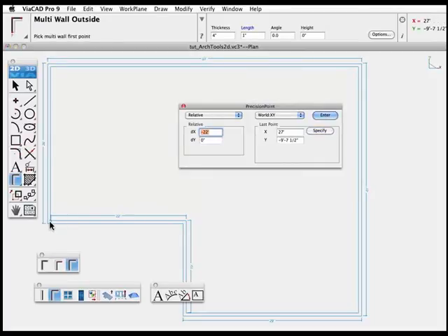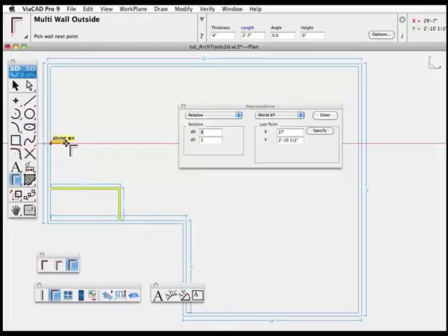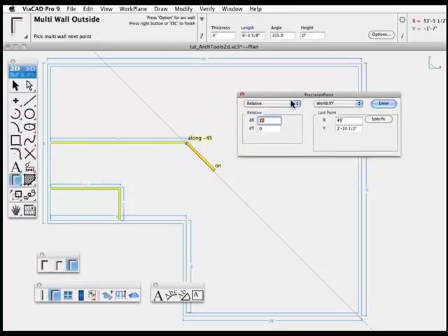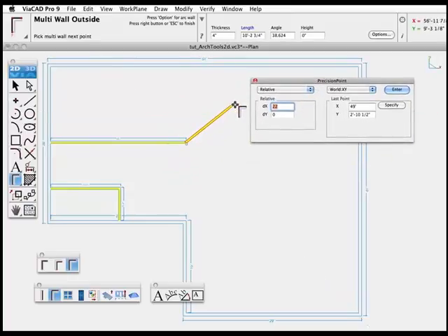So we'll click to set the point. Now enter the dy value of 5 feet, and that sets the start point 5 feet up from there. And then we'll use the logic cursor to place the other 2 points for our room. Click the midpoint. We'll drag out and set dx at 22 feet and dy at 0, and that sets a 22-foot wall, and then we'll just go up and set the other wall.